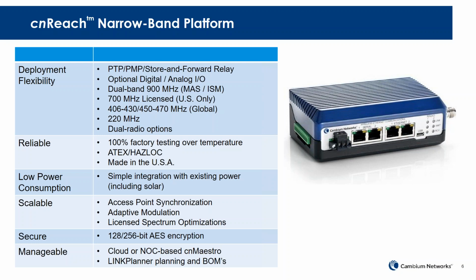I'll go through the bands. The product itself is tested 100% over temperature at the factory. That's done as a functional test from -40°C up to +70°C. As we step it through each temperature, the radios are connected in pairs and we make sure that they modulate and connect and work and function over all those temperatures. So the infant mortality rate is very low on this product, and the reliability is really sort of tested into it before it leaves the factory.